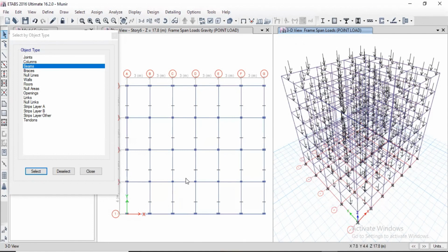That is in the cycling load. But here we do not apply the cycling load, we have to apply the point load and UDL, because on the structure this type of load acts. When we apply the point load, it means the load is acting in the form of axial load, for example on the column. And what is the UDL? When we apply the load of a wall on the beam, it is acting as a uniformly distributed load, that is the UDL. At every point the load is the same.